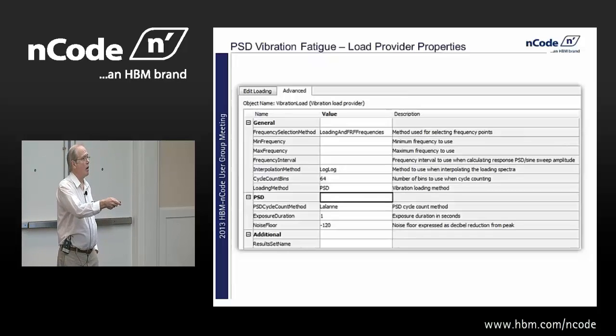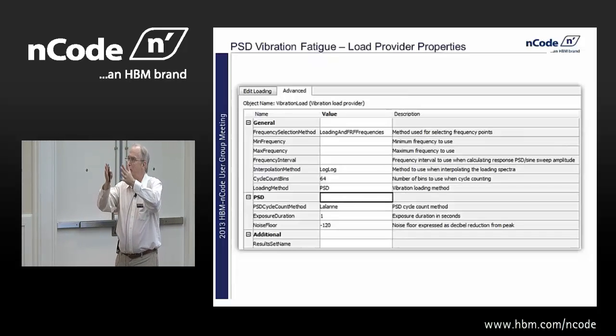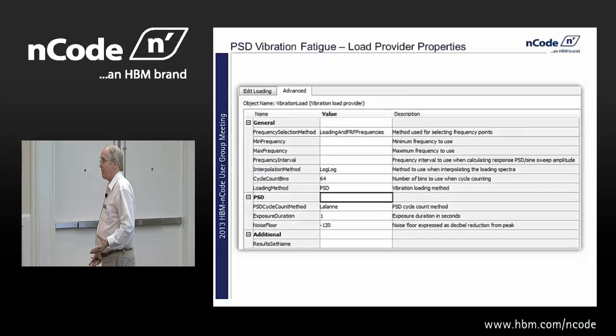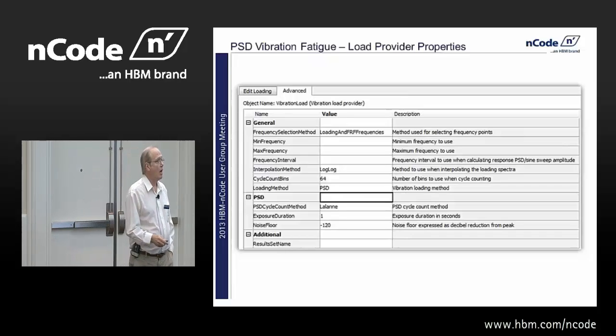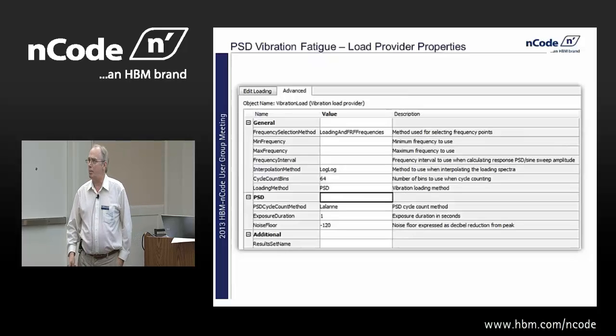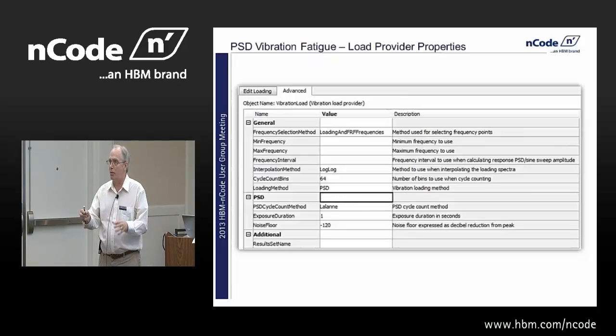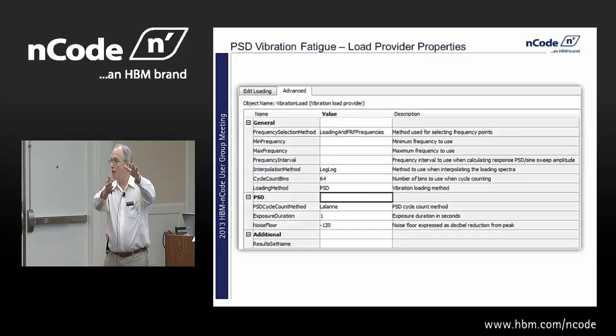And here's a setting that specifies at what frequency breakpoints I solve things. And we have basically a couple of options. I can use the frequencies coming in from the PSD. That's what loading means. And here's where that big difference comes in between bringing it in from a histogram or Excel. You know, it's whether I'm doing 5 calculations or 100. Okay.